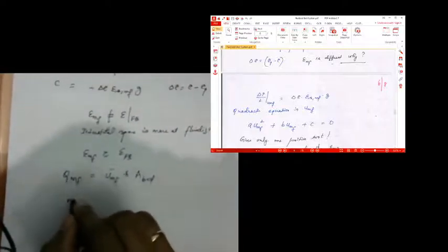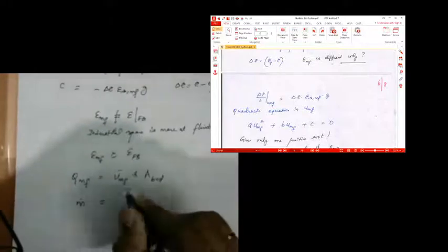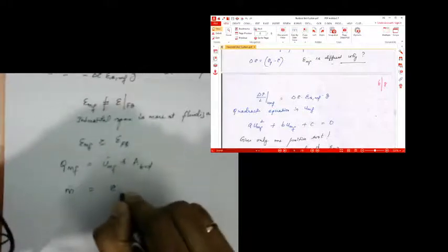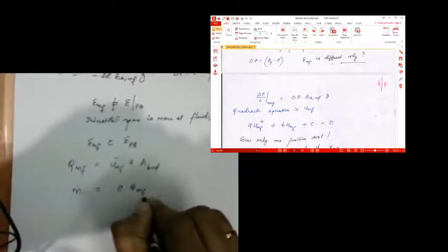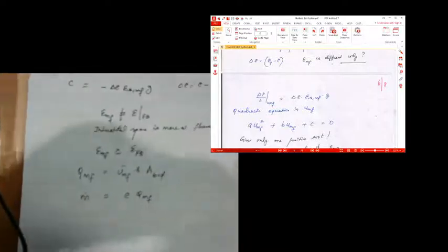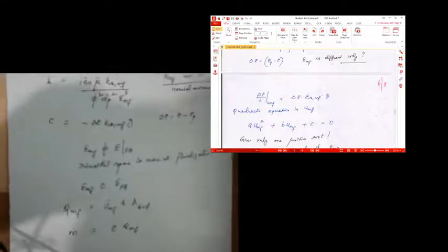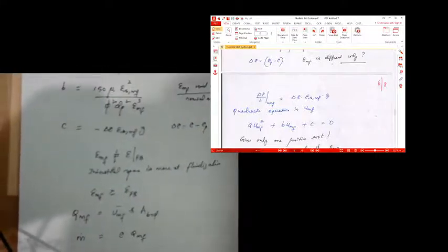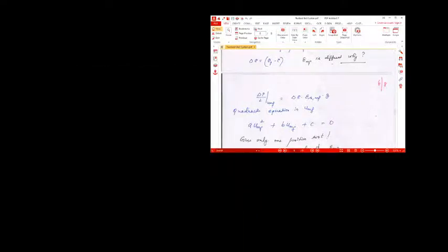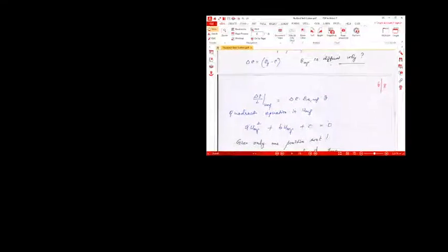And the mass flow rate of the fluid corresponding to minimum fluidization is the density of this fluid times the volumetric flow rate at the minimum fluidization. So this summarizes how one can get a minimum fluidization velocity or the transition point.